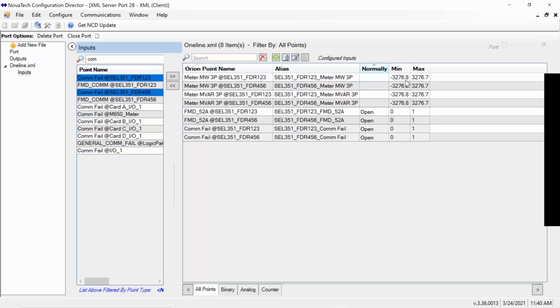And so in the case of recovering values at just a raw, say, minus 32,000 to positive 32,000 from a device, but we wanted to recover that decimal for the way that it's displayed on the XML portion or in Inkscape, as it's served into XML here, we might divide that value by 10 or by 100 or whatever decimal movement we need to recover those numbers and have them properly displayed on our Inkscape screen.